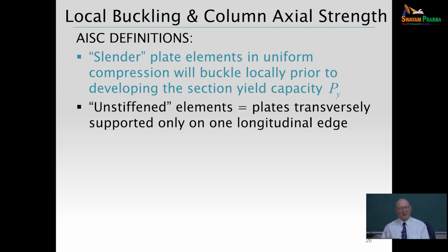In the Bridge Standard, we moved away from this because AASHTO wanted to go in the direction of basically being able to support design of anything from an HSS section up to a massive bridge tower with longitudinal stiffening. So clearly a plate with longitudinal stiffeners on it is different than what AISC is calling a stiffened plate.